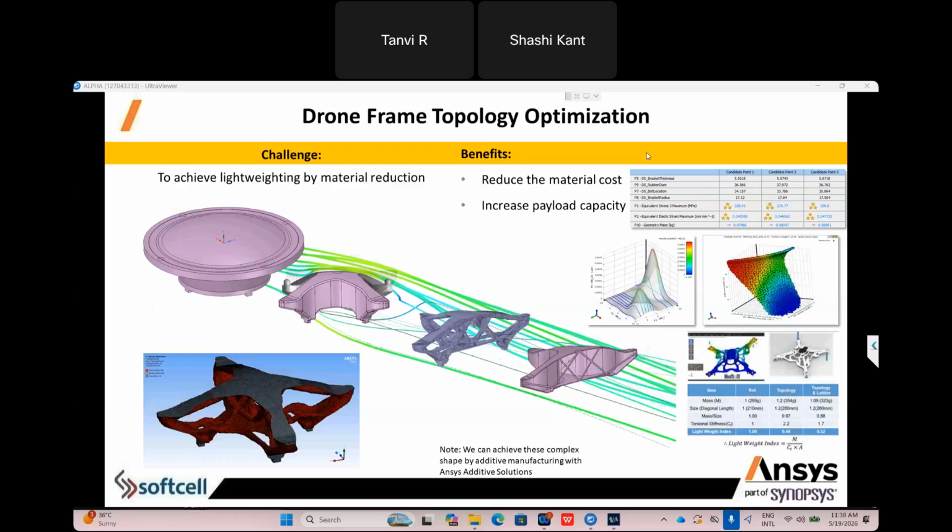Whatever optimization is done in the Ansys software, whatever design you have, what you can do, you can just export this file as an STL, and the STL file can be imported in any CAD modeling software. It may be SolidWorks, it may be Creo, it may be CATIA. You can import, you can create a manufacturing drawing. It gives you the optimized design of the eVTOL or structure, whatever you have. But honestly, if you do it physically, it will take a big time, and maybe you can do 10 iterations within 2 months, but this will give you the final design within 1 day or 2 days.